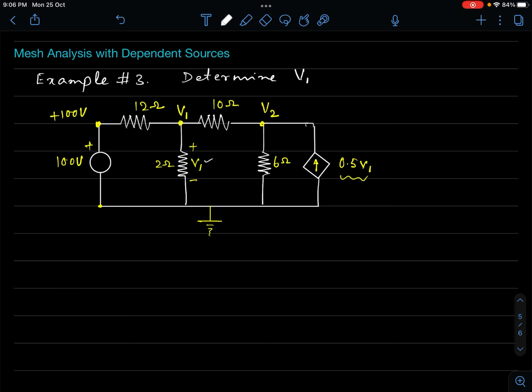If we can write the equations, we can write them by inspection. You can write the nodal equations by inspection. For a change, we will try by inspection. So it is the node V1 multiplied by the sum of the admittances at that node. Admittance is a generalized word, the reciprocal of impedance, but when we are seeing resistances in this network, we can even call it conductance, as a specific case.